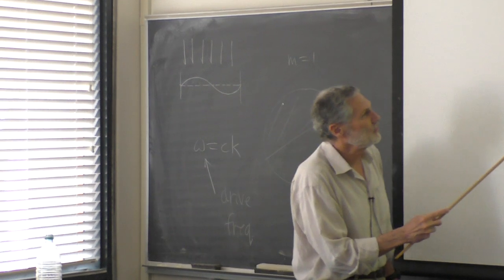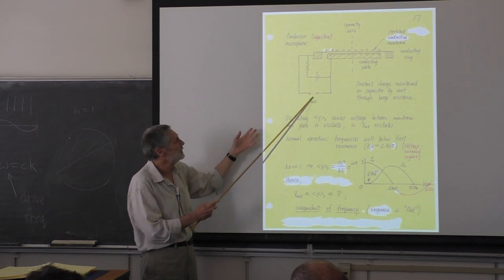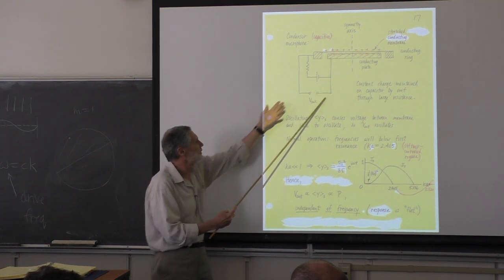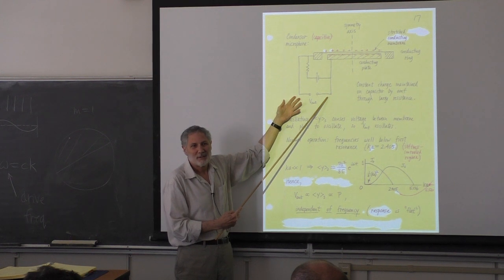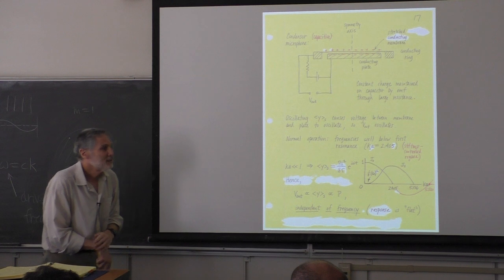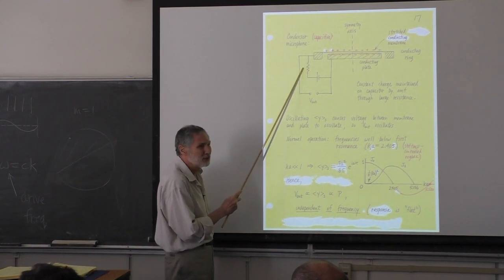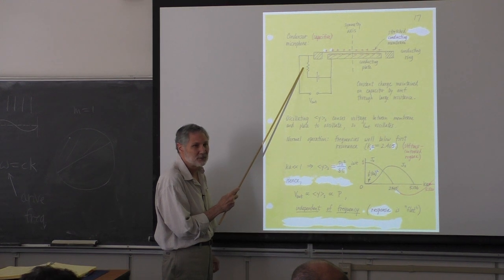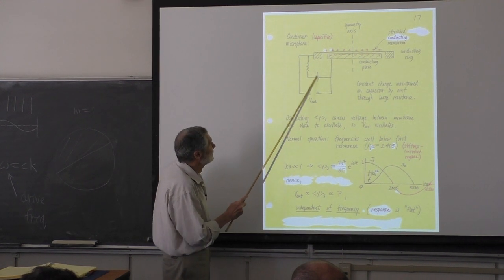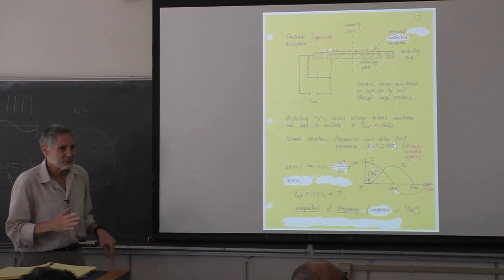Remember, we want to have a transducer here. We want to convert the sound to a voltage that's easily measured. If we keep the voltage across there, what are we going to pick up? Nothing. We're just going to see that voltage. We're not going to see the sound wave. So the trick is, and it's pretty simple, you want to put a resistor here. This will then have an RC time constant. Does that ring a bell? You make sure the time constant here is sufficiently long compared to the period of the acoustic wave.